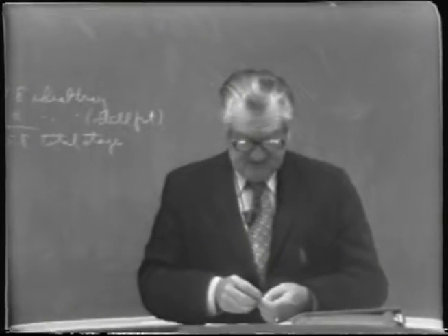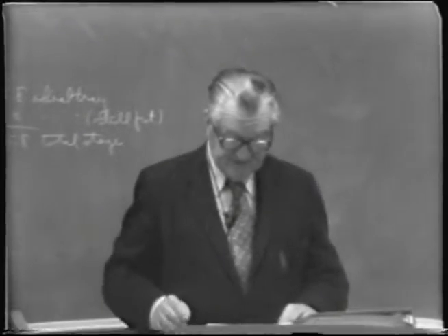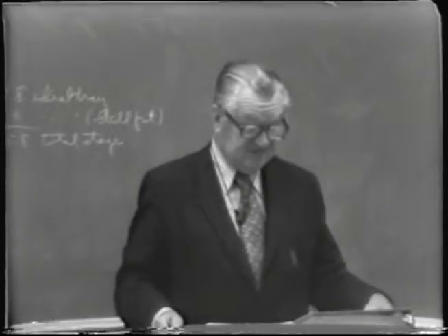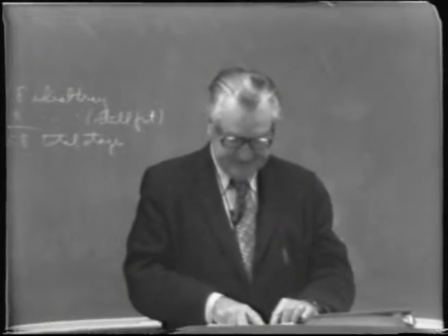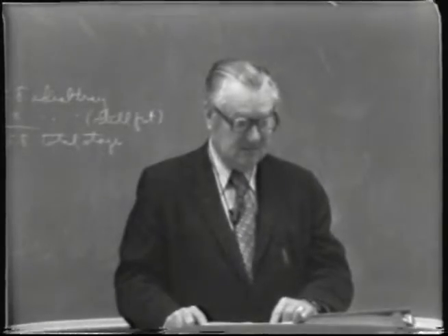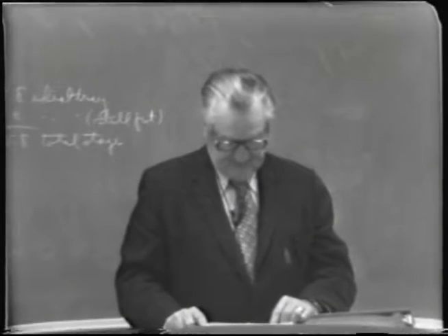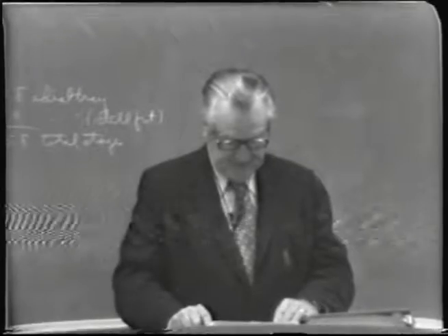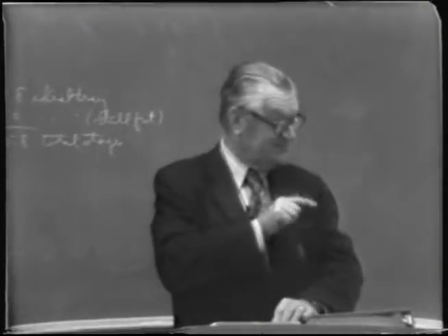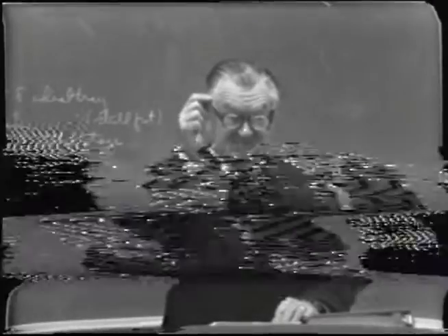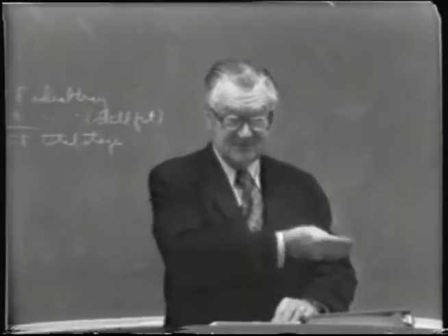So this is to illustrate the fact that we have a situation where we have two products. In other words, we have a heads from the condenser, and then we have a side stream product. So we have two operating lines, or the operating lines change as you come down from the condenser to the point of the side stream, and then it decreases in slope.